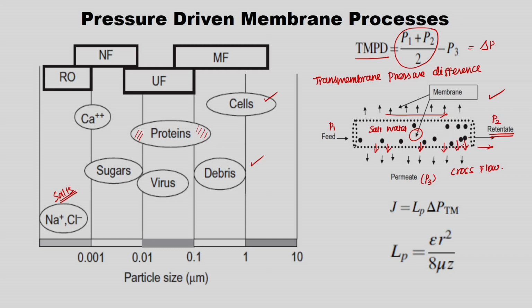To avoid that, sometimes the normal process can be changed so that the retentate is given back to the feed, to increase the suspension flow rate through the membrane. That is another approach one may follow, to avoid the salt concentration which is not carried over by the normal suspension flow.